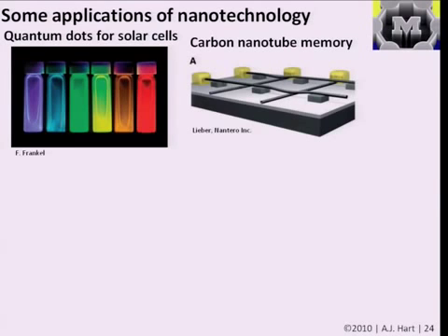So just like a bridge over a road, but what they theorized would happen is that if you applied a voltage between the bridge and the road, you could then, because of the electrostatic attraction due to the opposite charge, pull the top nanotube down onto the bottom one. And because of the strength of the intermolecular, interatomic forces, so-called van der Waals forces at that stage, if you turn the voltage off, they would stick. And then you could store that as a bit of information, a 1 or a 0, relative to the other state. And gee, if you could make this lattice very, very dense, and you could precisely control that gap, then you could store a high density of information.